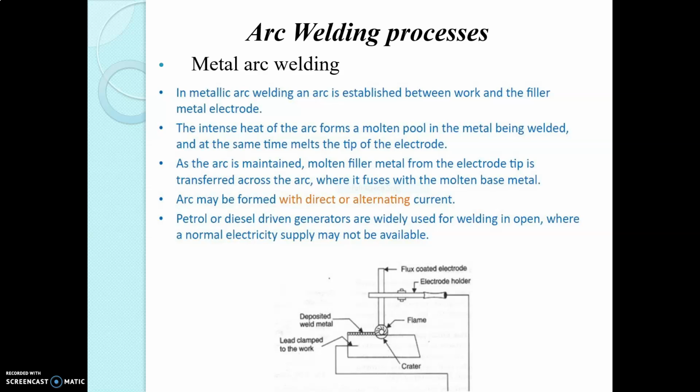Metal arc welding is normally a manual process. When the metal pieces to be joined are relatively thick, a number of individual passes are required to complete the welding process. The welding does not happen with only one pass; multiple passes are required. The line of metal deposited during a single pass is called a bead. By moving the electrode side to side, a wider bead may be obtained and more metal is deposited during the number of passes. So this is all about metal arc welding.